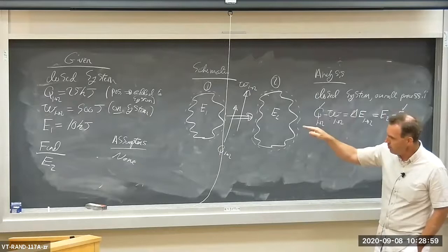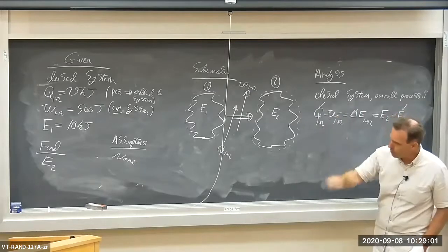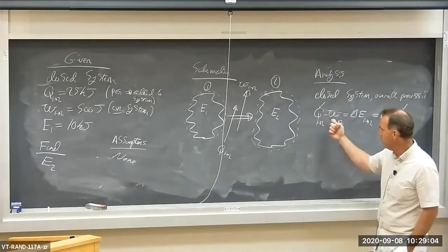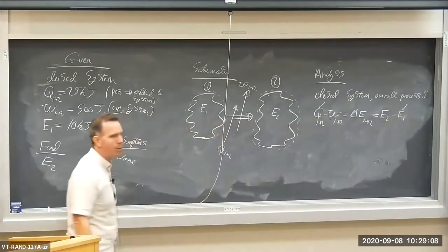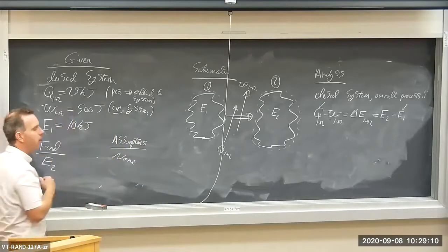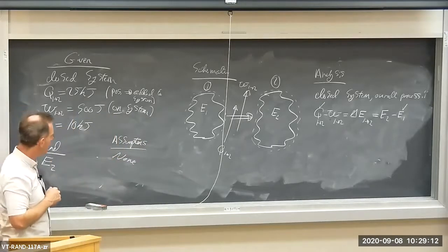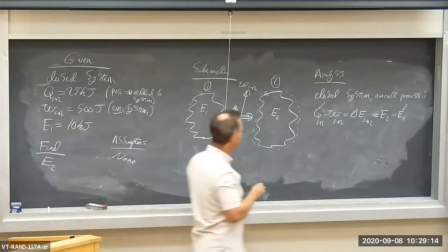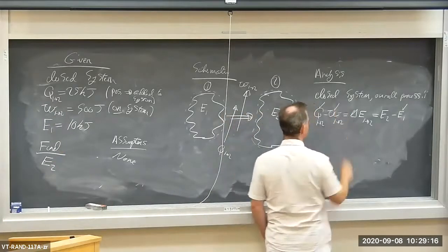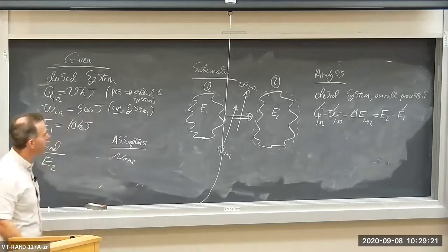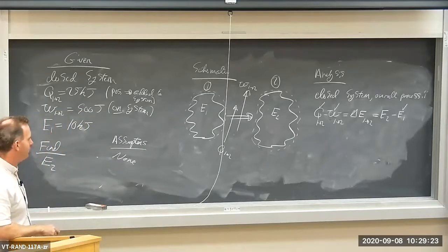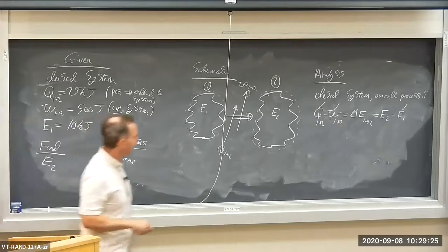On the system, we're doing work on the system by the amount of 500 joules, but the energy balance wants that to be written in terms of by the system, so I have to put a negative sign when I plug in the numerical value here, okay? Suffice to say, I have the work. I just need to put a negative sign in front of the numerical value when I plug in to make it by the system. Okay, so I got those three quantities here.